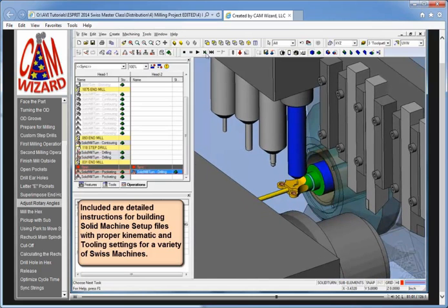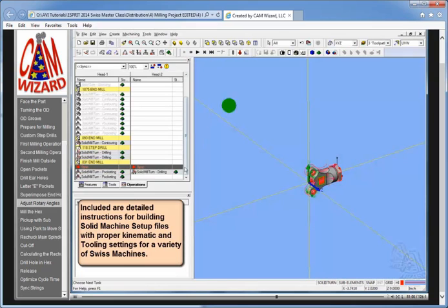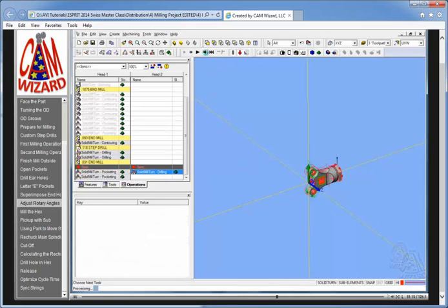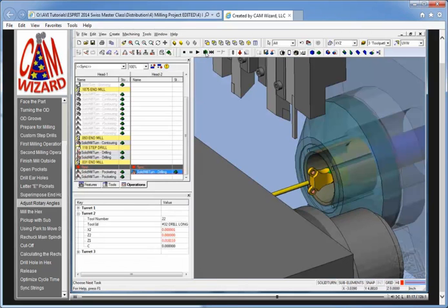And really that's probably not the best thing to do. What we really should have done is this drill right here. We might have rather indexed it 90 degrees prior to drilling the hole. In other words, if I try to drill that hole right now as it stands, it's designed to be drilled setting up straight this way.